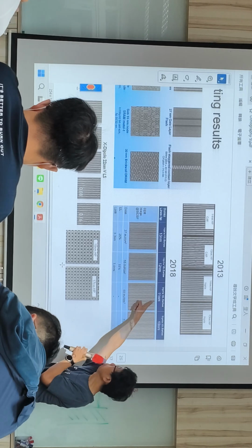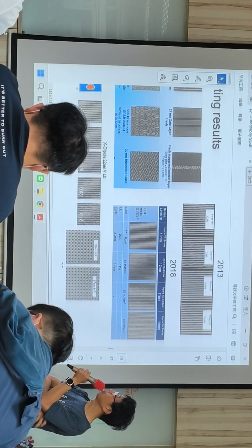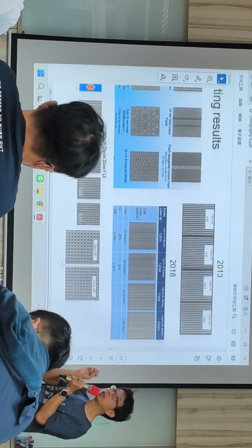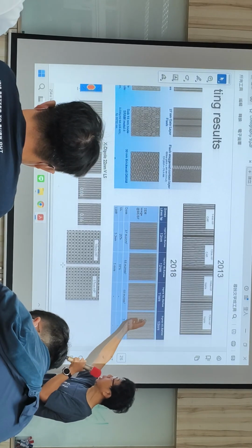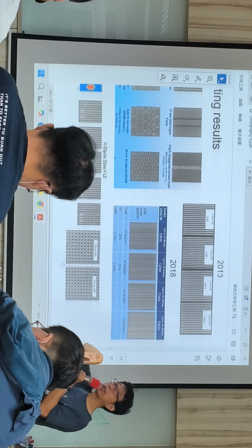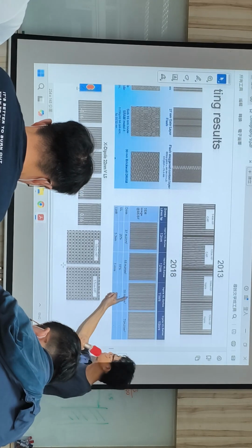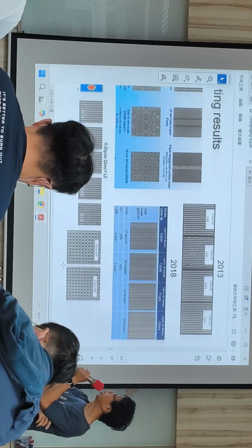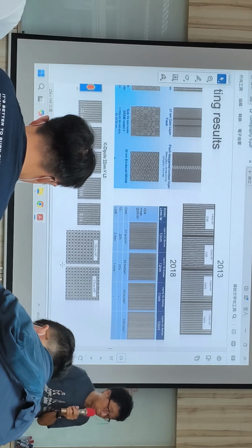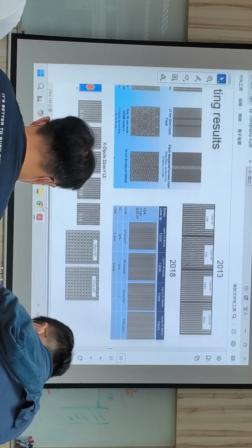This company called Inpria can do very high resolution images, but their resist is not CA. We call it a metal containing resist. It is not a chemically amplified photoresist, so they cannot do chemical amplification. They need a high dose to produce very straight lines. But at that time, they were kind of the champion at producing very small lines.